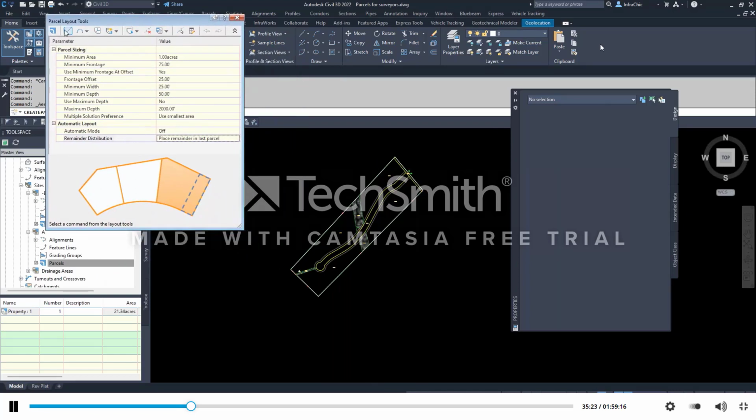That's awesome. Now, the first button over here is adding a fixed line. That will make a single line, point A to point B. That's all it does. It doesn't make a complete parcel. It just makes one line. Do I need to add an arc from a line? I can do it two different ways, three points or two points and a radius. This one is tangent to tangent with no curves, drawing tangent to tangent, continuous.